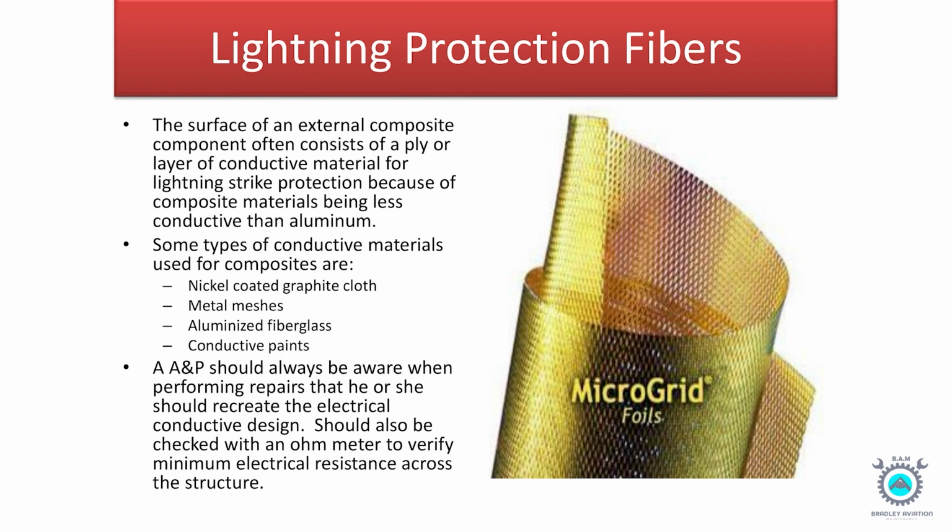The A&P should always be aware when performing repairs that he or she should recreate the electrically conductive design. It should also be checked with an ohmmeter to verify minimum electrical resistance across the structure.